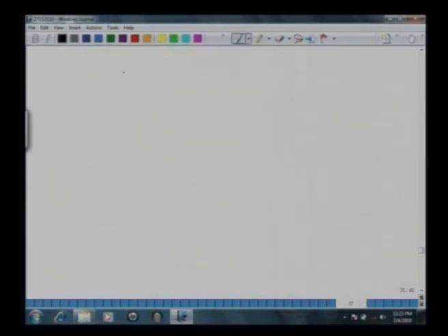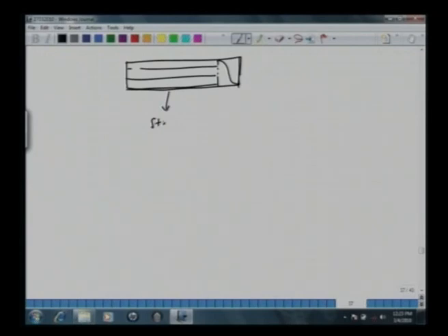Now if we plot further down, after some time you will expect that this MTZ has arrived almost at the exit. That means now the profile is like this, and this is the region which is now totally saturated. So this is a saturated zone, and this is a region where there is an activity, an active zone. Alright, so now we have reached the region of L3, and let's say L3 prime.